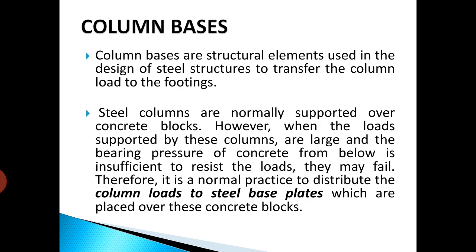So generally how do we transfer the load? Through the column the load is transferred to the foundation, and from the foundation the load is transferred to the soil. Here, in case of steel structure, if the column rests directly over the pedestal or the concrete footing, because of the high bearing pressure the foundation may fail.